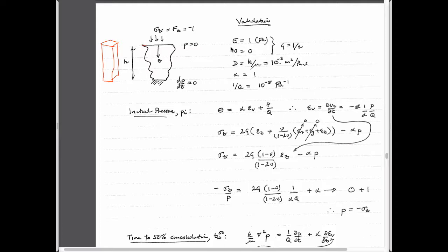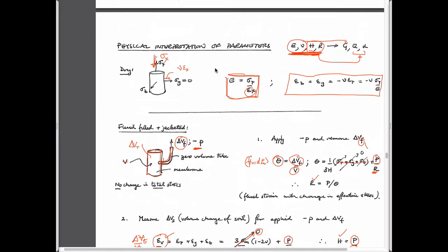I think, as we said before, we can make life easy for ourselves by having Poisson ratio of 0. The reason that you use cork in bottles is that it has a Poisson ratio of 0. Push the cork in the bottle, it doesn't snap the neck off. It doesn't expand laterally. And so if we use Poisson ratio of 0, it doesn't matter if we're plane strain or plane stress, the deformation that we get by applying some load is just going to be this magnitude here, because the other strains horizontally are not constrained.